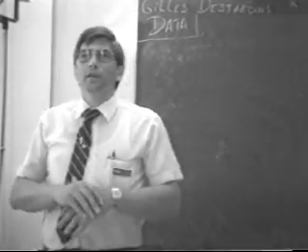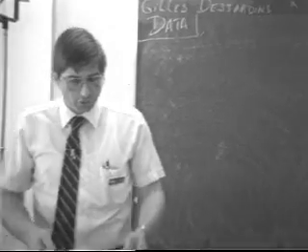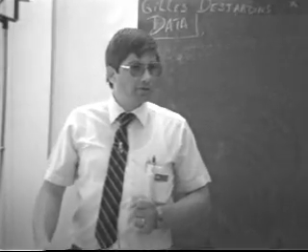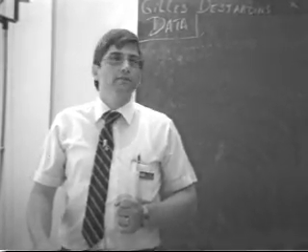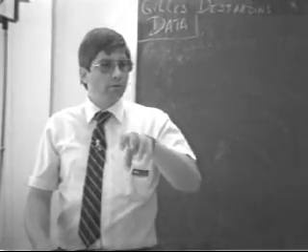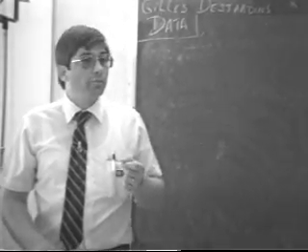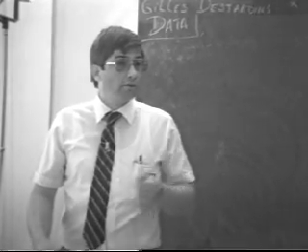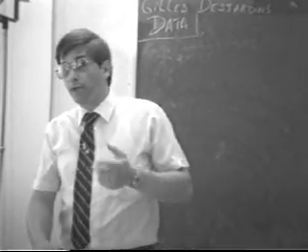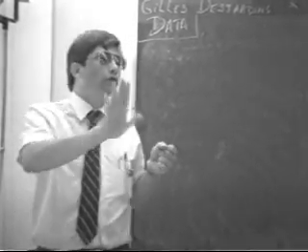So what happens to you when you determine that it is one particular CSS card that is not functional? You have put the card onto manual, you are single stepping through the card, and you find out that there's a problem. Now it's the microprocessor that's wrong, or it's the EEPROM that's wrong, you don't know. Well, first with the LEDs, you'll be able to determine if your PC is correctly going through the steps. And if it's your EEPROM, what would you do? What is the KLM's policy to repair? Repair to chip level? First of all, you replace the board and your simulator functions.